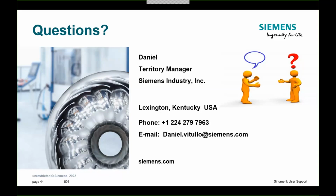You're not going to be able to simulate your 840. And here's the other piece of the puzzle. The programs you write, especially in ShopMill in SINUMERIK ONE, probably are not going to be compatible with your 840. Now, your 840 programs that you're running on your 840 will be compatible with your SINUMERIK ONE.